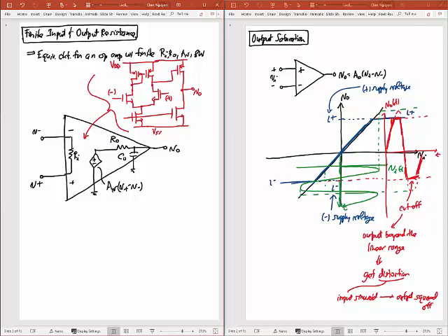And so I would size that capacitor if I wanted that op-amp transfer function that we all know very well now. So if I plot omega as a log plot there, and plot A of j omega as a dB plot, so that's the op-amp gain, then I expect it, like last time, to look something like this, where this is going to be A sub V, and this is going to be the 3 dB point, omega B. And if I want that 3 dB point omega B, I want to design that capacitor such that omega B is equal to 1 over R naught times that C naught that I put there.